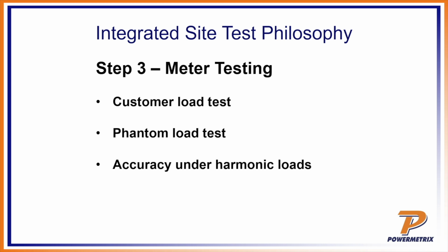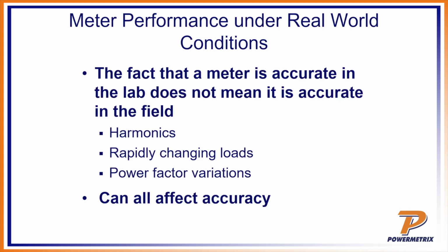And so the third step on the integrated site philosophy is the meter testing. I want to do a customer load test. I want to do a phantom load test. And I want to do accuracy under harmonic loads. Okay? So the fact that a meter is accurate in the lab does not mean that it is accurate in the field. Why is that?